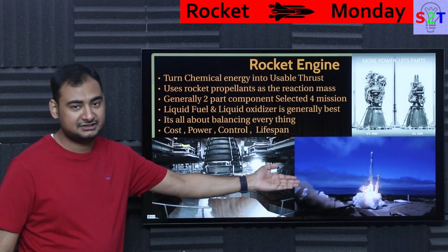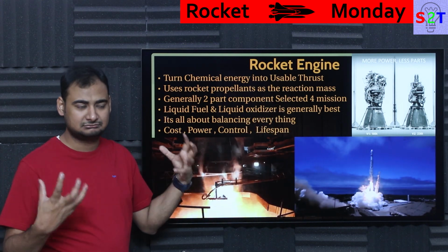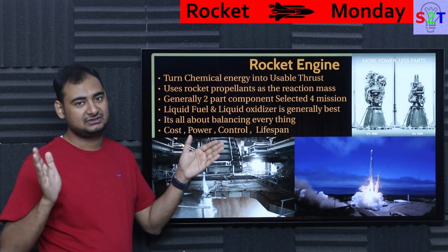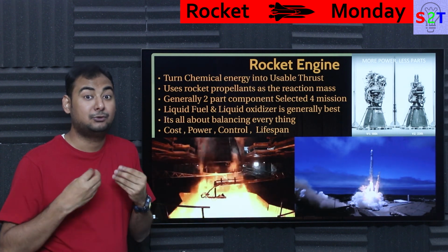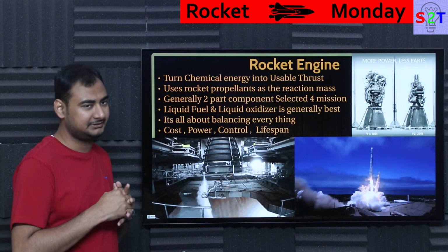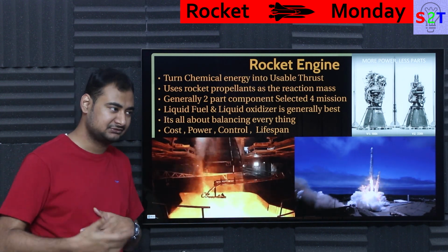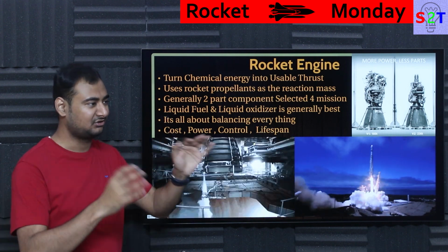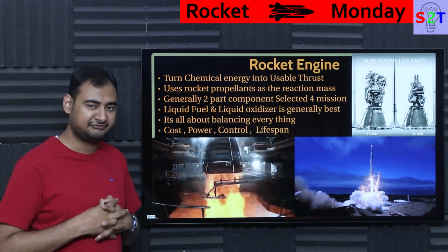And right now Merlin is the next big thing, and Merlin is using kerosene, so it's inherently very gummy kind of thing. Kerosene has very long hydrocarbons, and if you are burning them, many times it has the side effect of becoming polymer, plastic things, meaning it can gunk up your stuff very badly. So inherently there is a lifespan limit. They have to keep cleaning the engine, they have to keep cleaning the turbines. So generally after 10 times they just throw away the engine. It's just not worth cleaning it again. And again, it also has some other side effects of that.